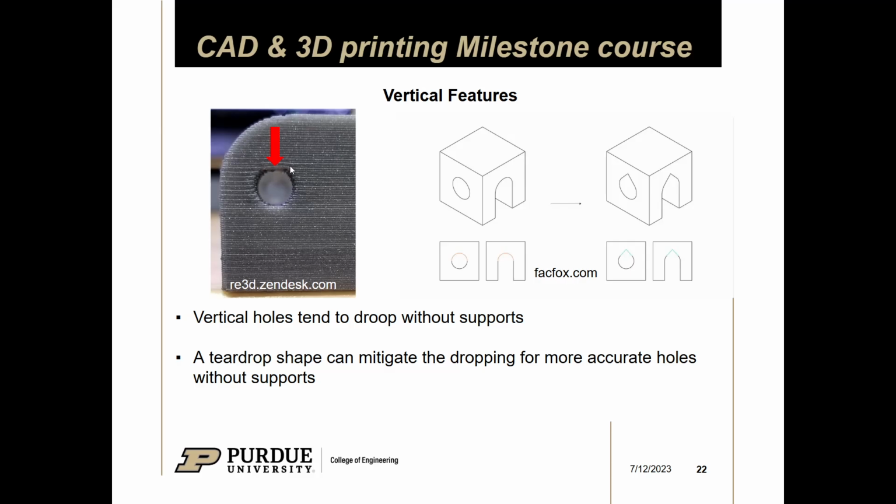And it's because the top of the hole is an overhang. So a good example, if you look at the front of the hull, there's these two little anchor holes where the anchor would run through. So if you don't have adequate cooling on your 3D printer, those holes can droop, right? Again, depending on the benchy you got from me, those holes may look more or less round, but that's just something to keep in mind, right?